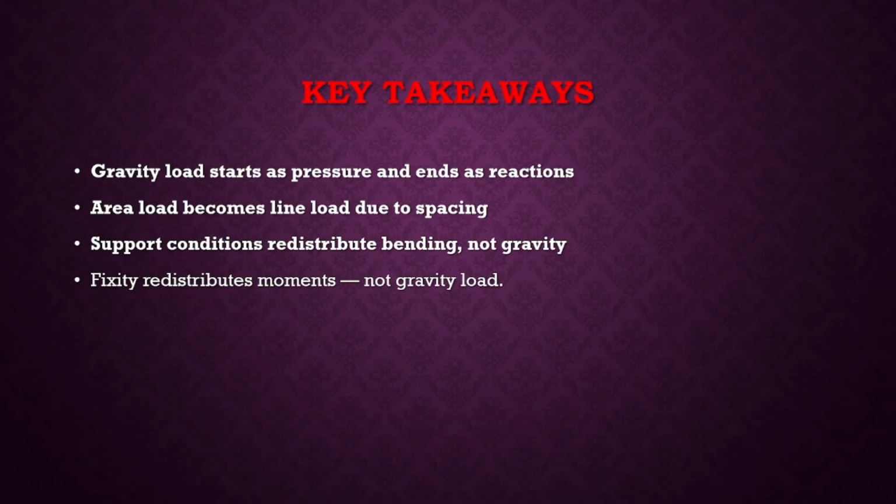So what are the key takeaways from this video? We understood how gravity load starts as pressure and ends as reaction. We understood how area load becomes line load due to spacing. If you increase this spacing, the UDL on your member will be more. If you decrease this spacing, again the UDL will be less. We also understood how support condition redistributes bending, not gravity.